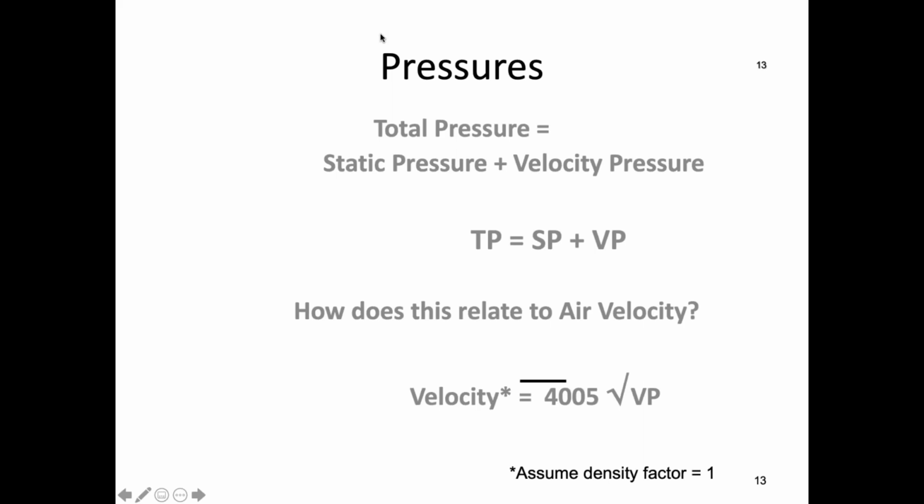So if the wind is blowing at 20 miles an hour, the pressure in whatever measurement we want to use, PSI or atmospheres, or very frequently, when we're measuring air pressure, especially in indoor air situations, we usually use a measurement called inches of water. In other words, the pressure against our face is the same thing as feeling the weight of 1 inch of water or 2 inches of water. So if a 20-mile wind is blowing into our face, we might sense that as the equivalent pressure of 4 inches of water, and that's the way we would describe it. A 5-mile-an-hour wind would be lower.